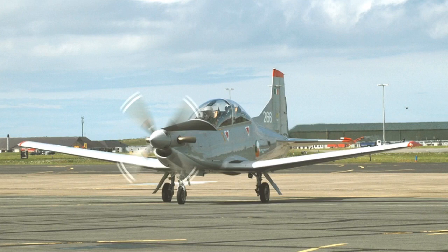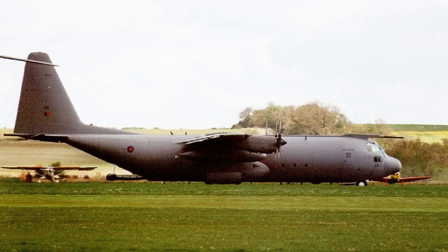The propeller of a free power turbine engine can be held at low RPM during taxiing, thereby reducing noise pollution and wear on the brakes. A free power turbine engine requires less starting torque than does an engine where the turbines and compressors are coupled together. A rotor parking brake can be fitted to an engine with a free power turbine. This eliminates the dangers inherent in having propellers rotating in windy conditions on the ground.